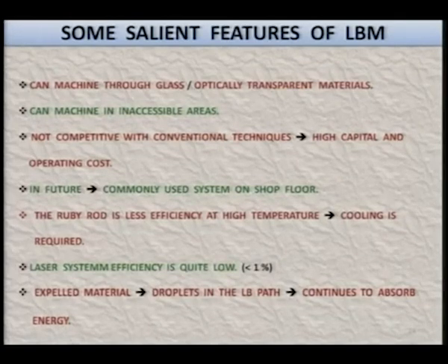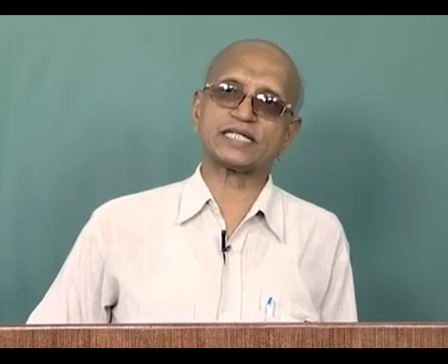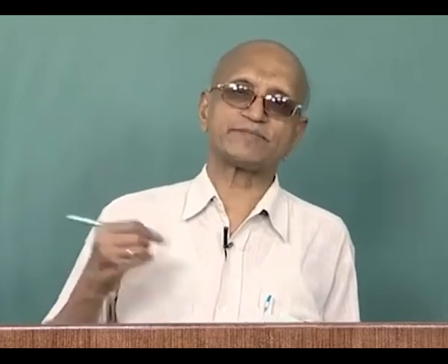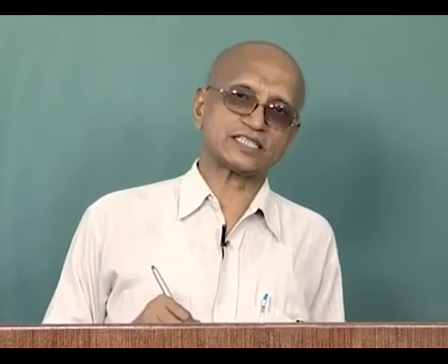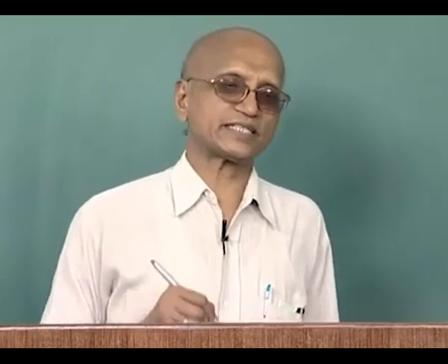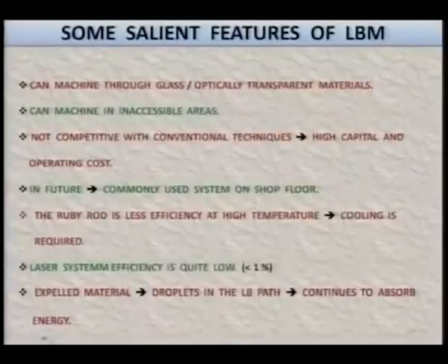Now, what happens is that whatever is the expelled molten material from the groove, when it again comes in contact with the laser beam, it absorbs a large amount of heat, and as a result the same material gets resolidified, again takes the beam energy and gets evaporated and then gets solidified and so on, and because of this process also the efficiency of the laser beam machining is quite low compared to other factors also.